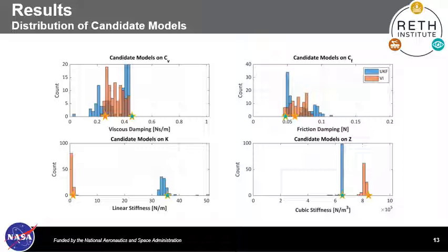of the resulting posteriors. However, regardless of the differences in the best solution, the overall results do show a lot of similarity. The mode of the models aligns well with whatever that best solution is, and the confidence with which the stiffness parameters are inferred exceeds that for which the damping parameters are inferred, for both inference approaches.